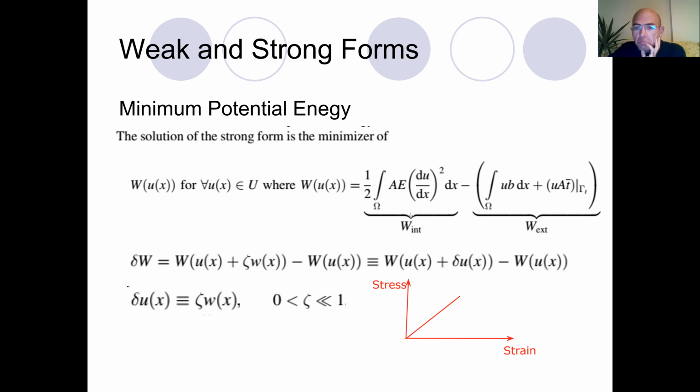Therefore the energy stored inside the material is basically the area under this curve. If you calculate the area under this curve, that gives you the strain energy, and that's equal to 0.5 multiplied by the stress multiplied by the strain. That's equal to the strain energy.